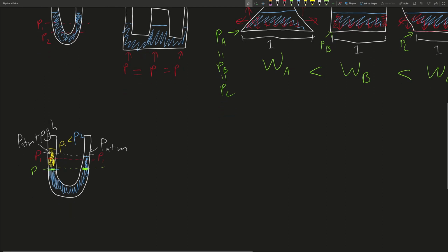But then anything underneath this line where it divides it, we see the fluid is just the same. So the pressure is going to be the same given that the height is the same, as long as the fluid remains constant and the density remains constant. So since this section has constant density, then the pressure is going to be the same at the same heights.